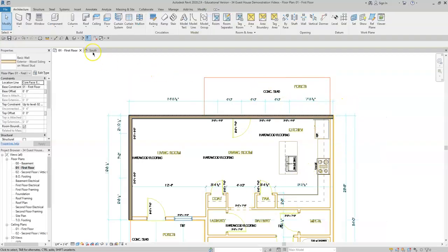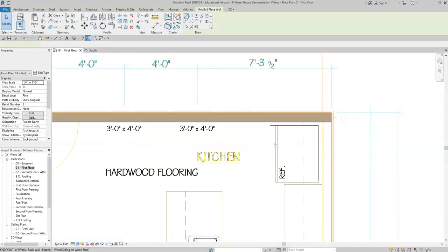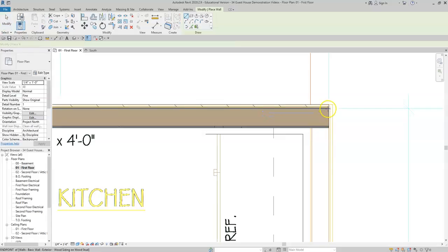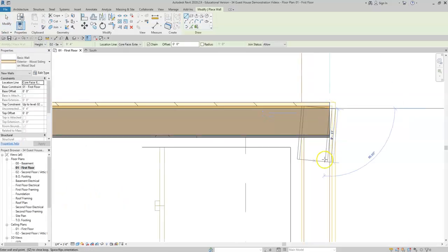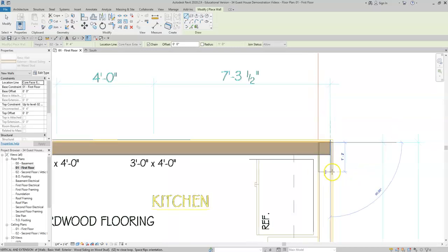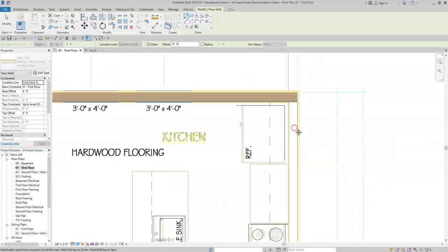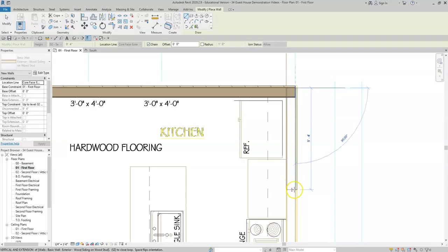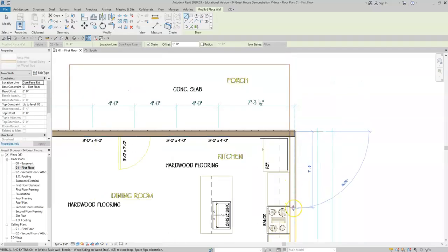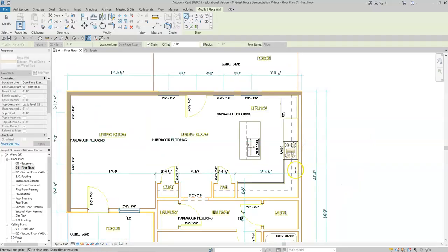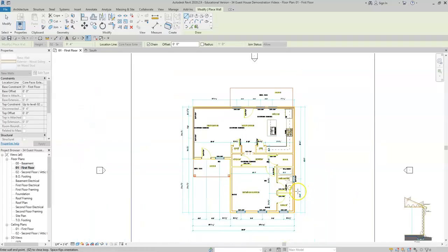To continue our drawing or our model, we will select wall again. We will choose the core face. And we will continue typing and moving and modifying and shaping our exterior as noted on the 2D blueprint which you were given in the classroom. We have another 34-foot dimension, 34 feet.